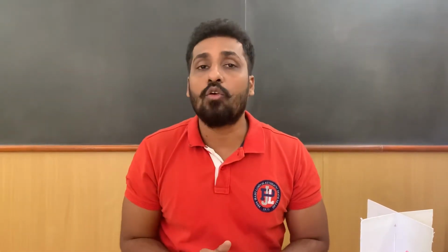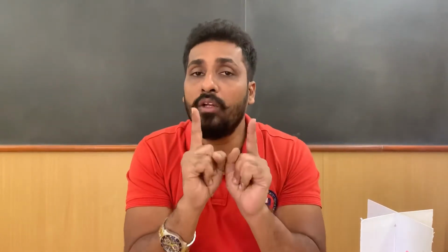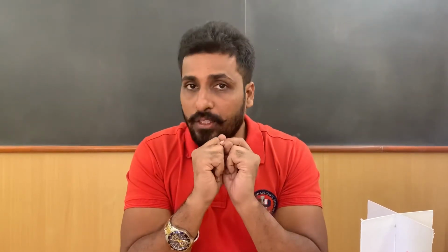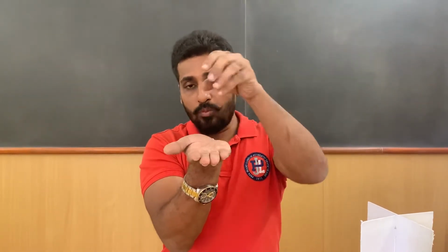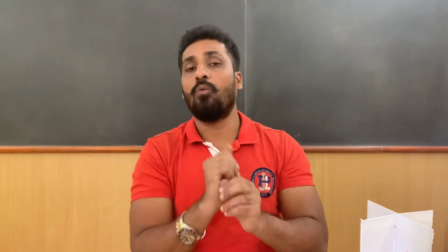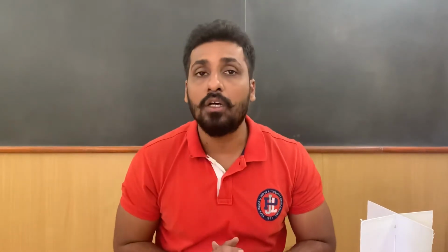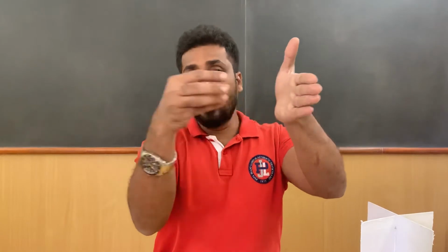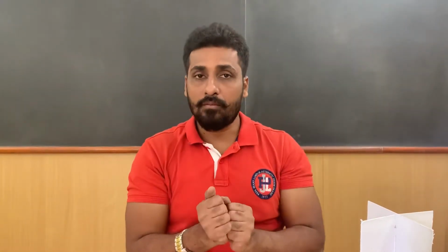Let's talk about the second quadrant. So we take a second quadrant. So in second quadrant, always remember, only the horizontal plane is going to move, and that too always in the clockwise direction. So if I take the second quadrant, that's the horizontal plane, that's the vertical plane, object is kept here. So I'm going to watch the object. So the front view and the top view, as I said, front view will always fall on the vertical plane, the top view will always fall on the horizontal plane.